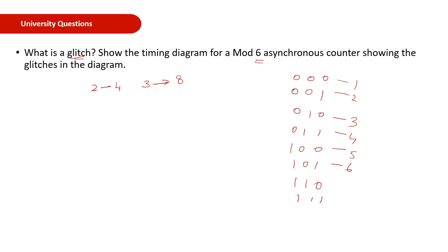When the sixth state is occurring in a 3-bit counter, the next state will be 110, but you require the states only up to 101. So you have to check whether the next state, the 7th state, is occurring. When the 7th state is occurring, you have to reset all the flip-flops. We will do this with the help of a NAND gate, where the inputs are QA, QB and QC, supposing those are the names you give your flip-flop outputs.